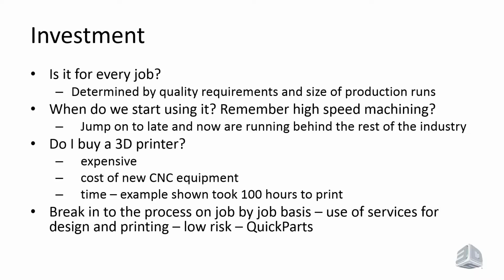Whereas because we're not used to thinking about conformal cooling, we're uncertain as to what jobs are going to go into a 3D printer. So it's something to investigate, and it's something to think about in terms of how we're investing the years to come in our business. And we have to figure in the time it takes to print something. That example I showed you, remember what it was, right? 3.5, 5 inches. It took 100 hours to print that little core. So your printers are going to be busy printing cores if you go this route to achieve conformal cooling.